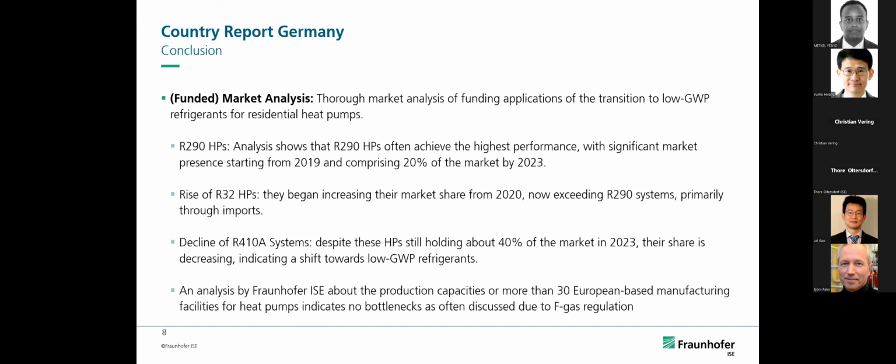The data which were published usually just have a general look at what refrigerant heat pump production capacities are, and they have not had a look into the refrigerant-specific production facilities. And we can state that just for the air-to-water heat pump market, right now, there won't be any future issues in terms of supply. So that means it would be easy to go for the air-to-water heat pump market and flood it actually with R290 heat pumps right now.